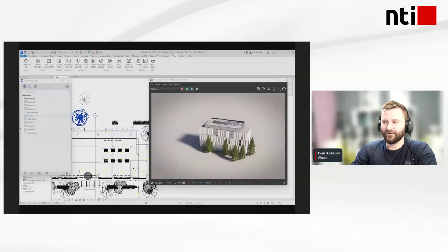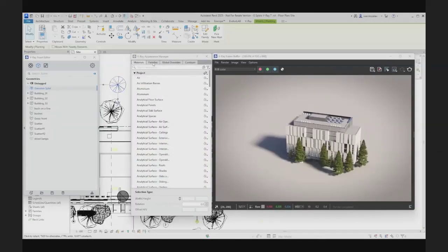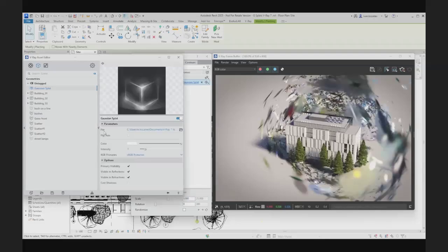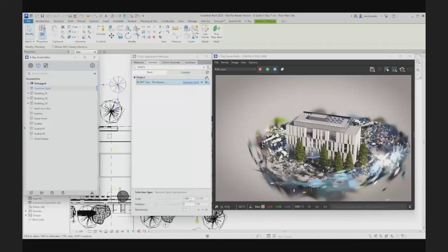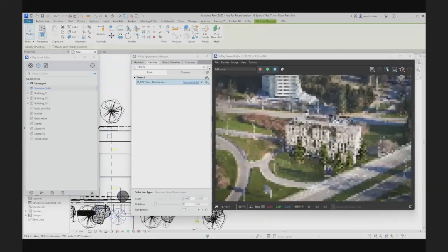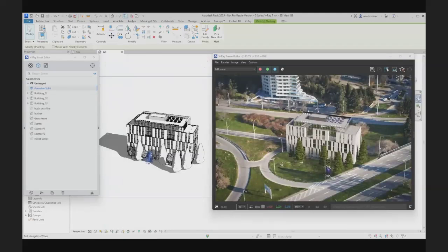Basically, if we want to have the perfect environment for our projects, we can take some pictures with a drone, or hire someone with a drone to take a video, and then we can generate them thanks to artificial intelligence. This is suitable for a lot of projects, because with drone pictures, we can generate a file that we can use in V-Ray, and we can set it really easy and really fast. Load the file and then set it right here, move it up on the project until we match the Gaussian splat with the building, and we can achieve really good results.